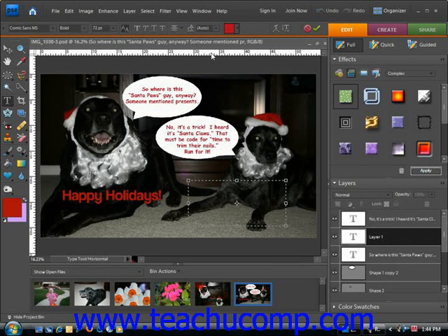Unlike point text, however, you do not need to press Enter to create a new line within the same paragraph, as the text will automatically wrap when it encounters the edge of the bounding box. If you type more text than the bounding box can hold, you'll see a small icon appear that looks like a square divided into 4 quadrants. The icon indicates that the text is overflowing the bounding box. You can resize, rotate, or skew the bounding box to adjust it to meet your needs.